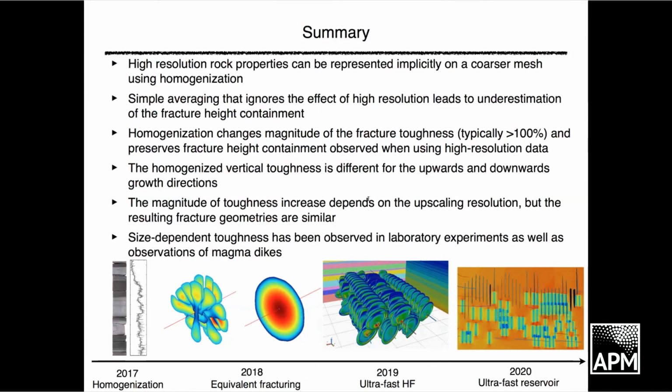This is one thing. And the second thing, even in the P3D model, the horizontal growth is controlled by viscosity, but the vertical growth is very often controlled by stresses and toughness. So this is a main assumption of the P3D model, that the fracture propagates in the toughness regime vertically, and once you propagate in the toughness regime vertically, then toughness is important. I got your point.